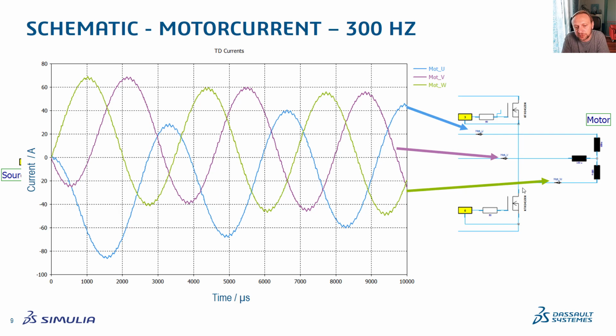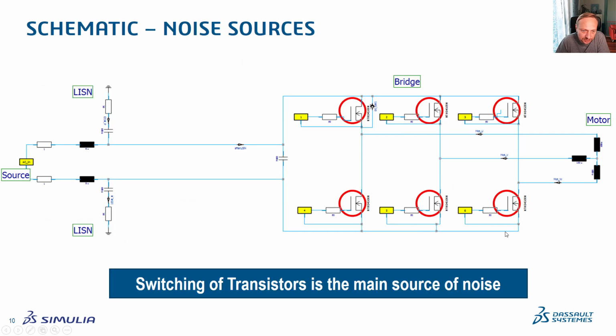Depending on what kind of PWM you apply, you can of course have different values here. You might have a different PWM frequency or a different value of the sine going out to the motor, because that's the frequency which is proportional to the rotational frequency of the motor. But it does not mean that at 300 hertz you will have 300 rotations of the motor in a second, because it depends on the topology of the motor, how many poles you have and so on. But I'm not a motor expert, so I'm not talking about motors too much. We talk about the power electronics section.